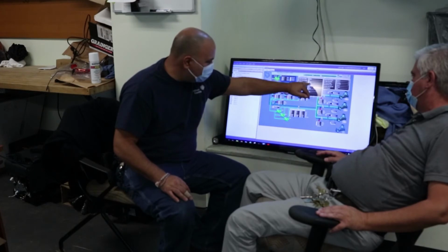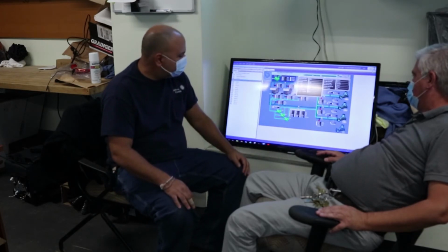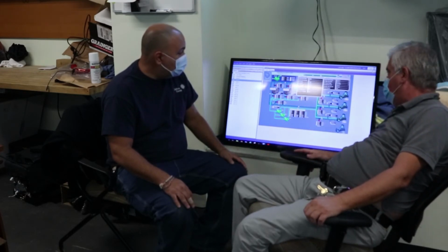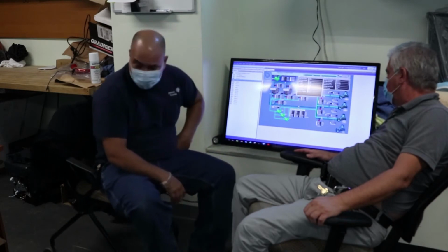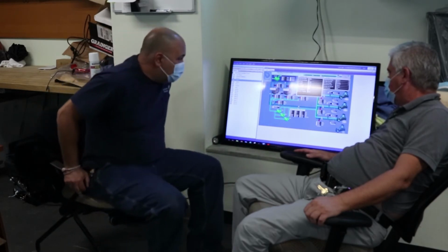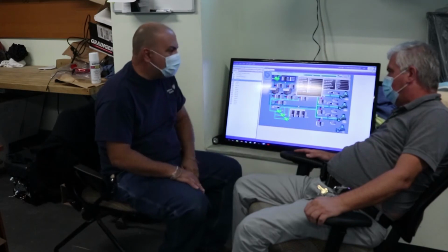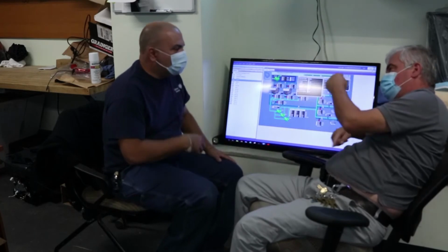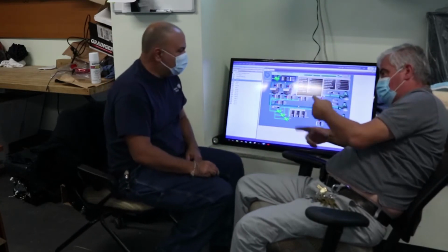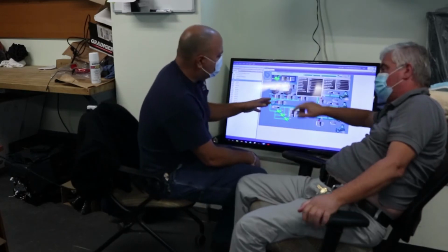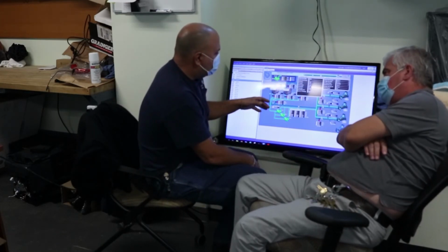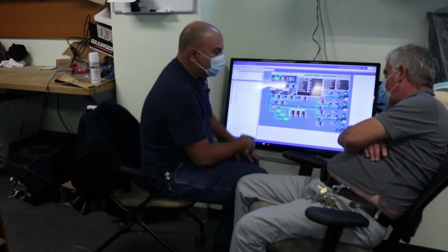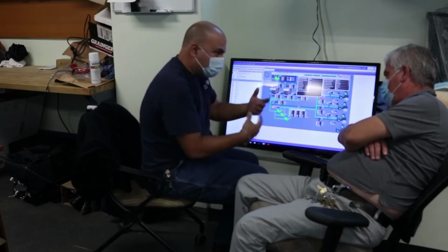This same thing will rotate your pumps. This is based on run hours. The cooling towers might be on run hours too. Everything will be on run hours, so it'll go every 3 days. But for pumps, it should be on run hours. Everything's on run hours, but it's a matter of when it rotates. So it's not when it hits 100 run hours that it rotates.